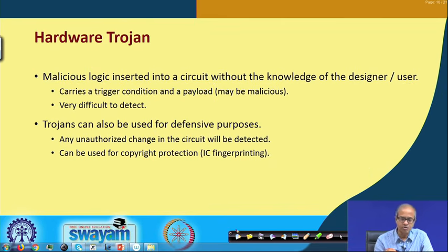Well, these Trojans can also be used from the other side, from the ethical side also, like you can use it for defensive purpose. Like when you are designing an IC chip, you want that someone should not steal your design. So, you deliberately insert a Trojan yourself whose behavior will only be known to you. So, someone else who is copying your design will also be copying the Trojan along with that. Whenever the Trojan wakes up, that person will not know what to do with that Trojan. Okay? So, it will be unusable, the circuit will become unusable.